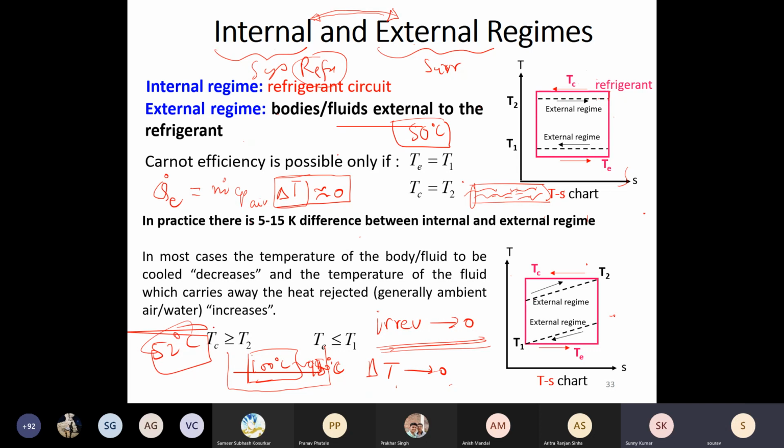It means that your condenser will still be able to condense at 52 degrees C. Does that mean the condenser is operating at 52? No, it is operating at maybe 5 or 10 degrees higher than 52. So your condenser is rated to cool your refrigerant vapor even at 60, 62, 65 degrees. It depends on how much delta T the designer has chosen.